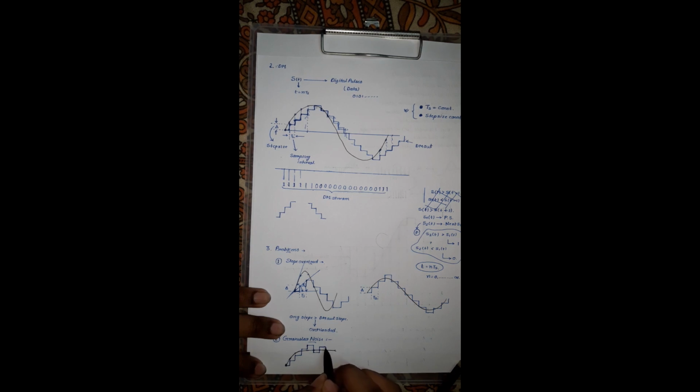After producing the upstep, after a particular time, it is comparing this amplitude of the black input signal with the last sample amplitude. Again, a downstep is produced. After this downstep, after a particular time, it is holding this sample value, and after a particular time, it is again saying that this amplitude of the original signal at the particular time is greater than the last sample amplitude. Again, it is producing an upstep.